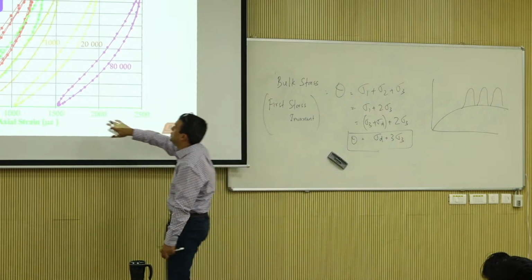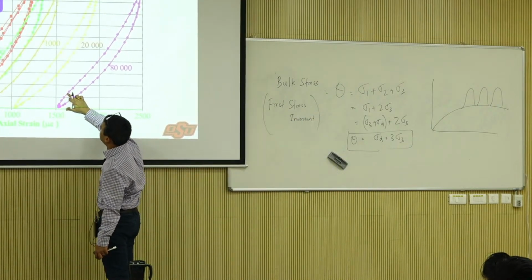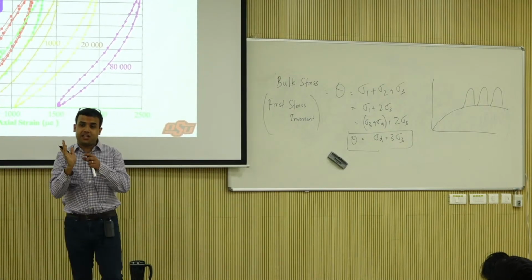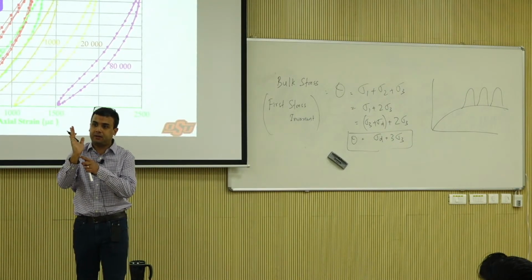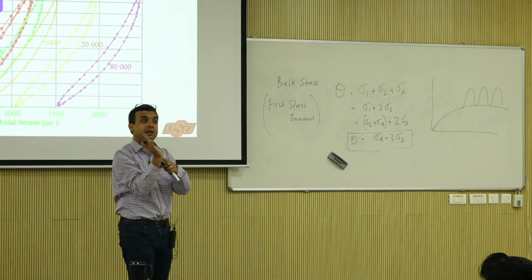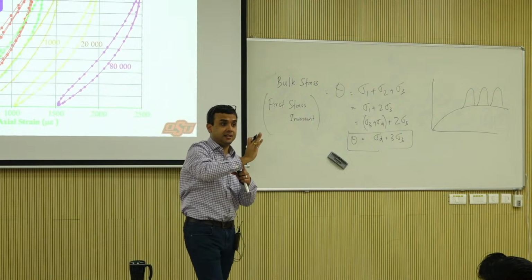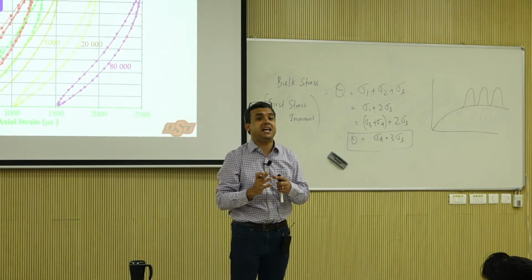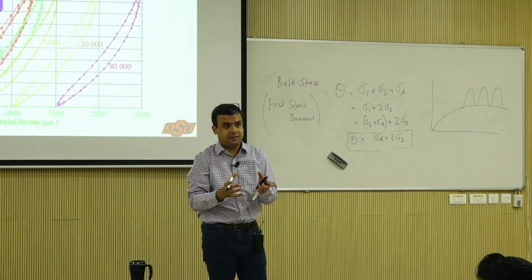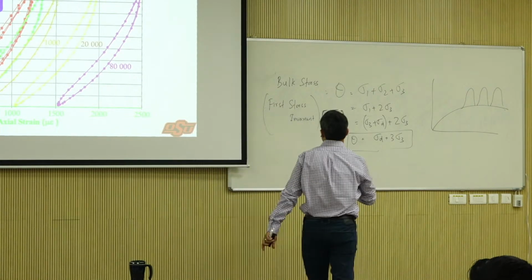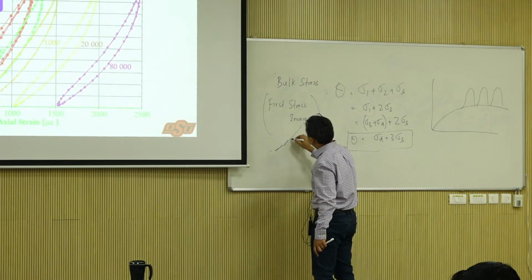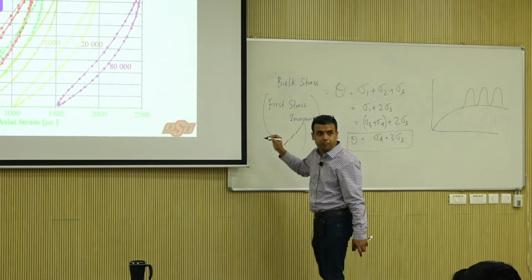If you do a tangential modulus here, you do tangent, tangent, tangent, tangent, the tangent actually keeps rotating up, right? So the modulus value increases, right? So that's called a stress hardening material, because stress hardening is basically you're going to have the tangent rotate upwards.